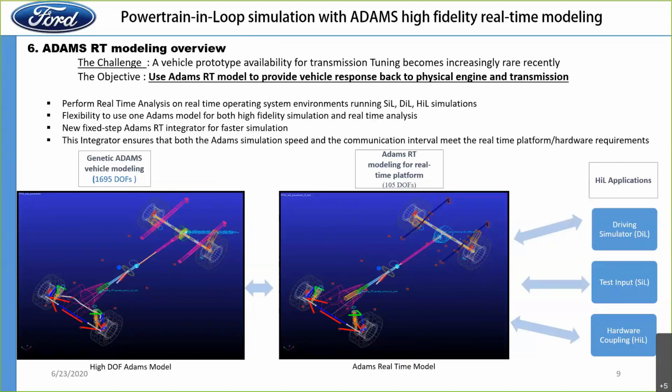The foundation for how we reduce this is just as described by the previous speaker. We check the model frequency, and we only keep the modes at 50 hertz and below, and we want to run the model at 25 to 30 hertz for the transient behavior.